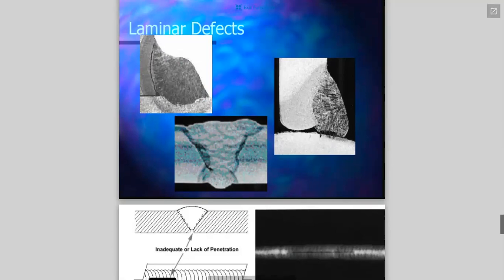In this case here, yeah, we got some great bonding here. This is all cold lap on the bottom. It's just kind of laying there. The person never pointed the welder at that.